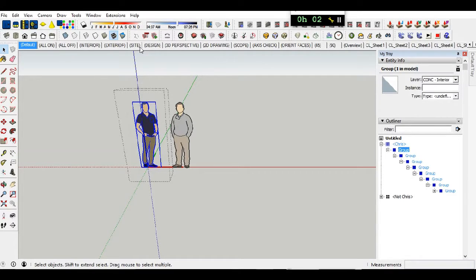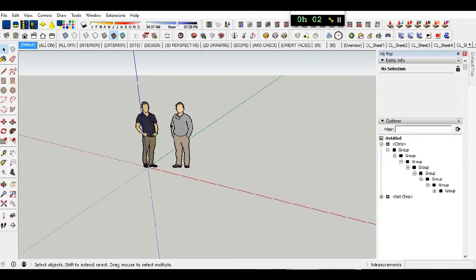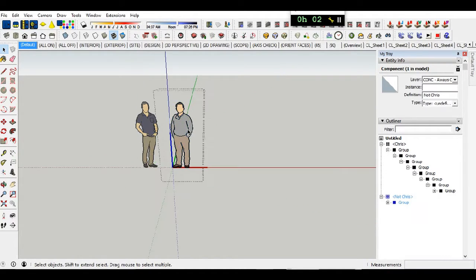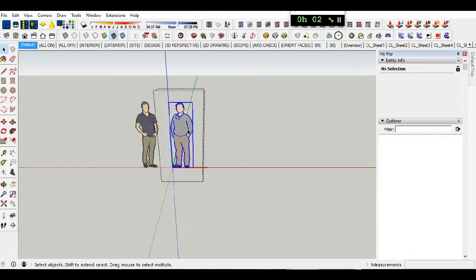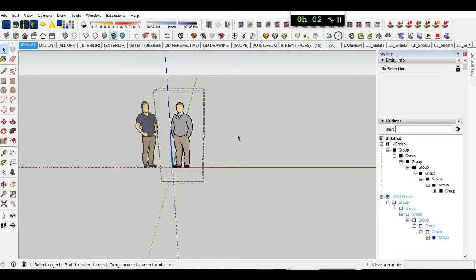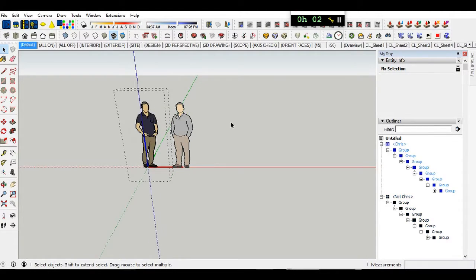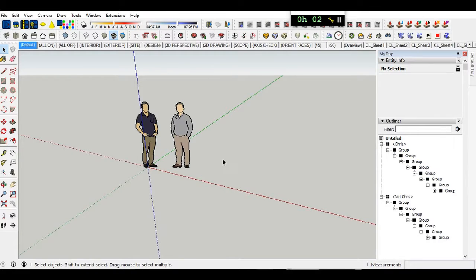If I'm drawing in the regular 90-degree view and there's a room, you'll see on this floor plan that we're getting ready to work on, if there's a room that is offset by 45 degrees, I can toggle these two scenes to change the axes, and then it'll be easier to draw in that 45-degree angled room.